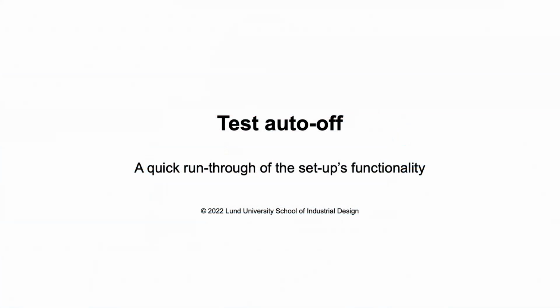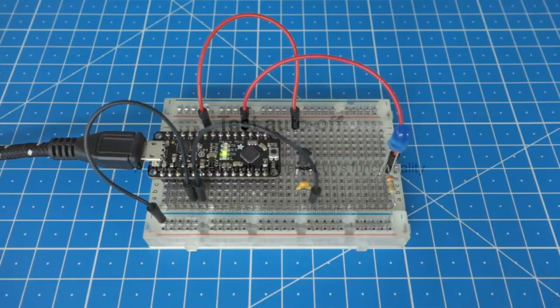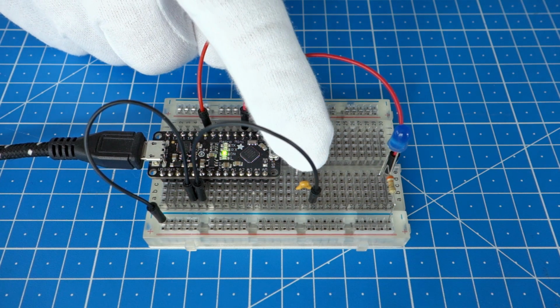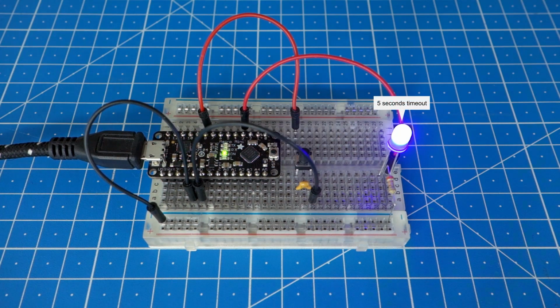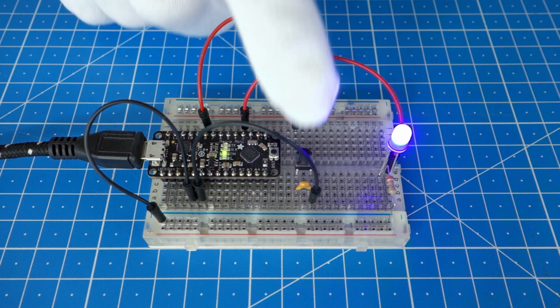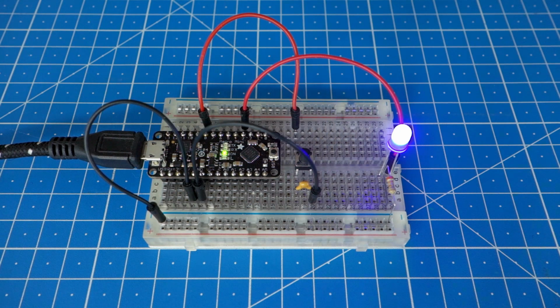Setup 2. Setting an auto-off timer. Here we start a millis timer upon releasing the button. The timer is not blocking other running code, and you can set any duration, whether milliseconds, minutes or hours. You can also use other events to start the timer, and you could have more than just one. Look at the code with detailed explanations for how this is done.